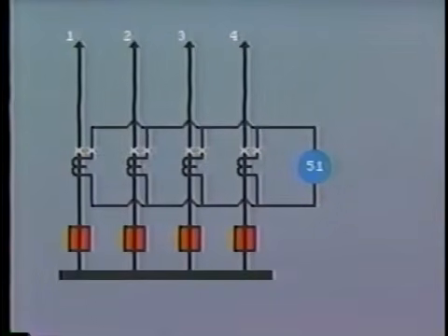Another method of providing high-speed differential bus protection is by the use of high impedance relays. Actually, this type of protection offers more than just high impedance, as we shall see. Let's go back to our simple current differential that we have already discussed. As we know, one major problem with this relay is that it may inadvertently trip for external faults due to the transient surge when the fault is initiated.